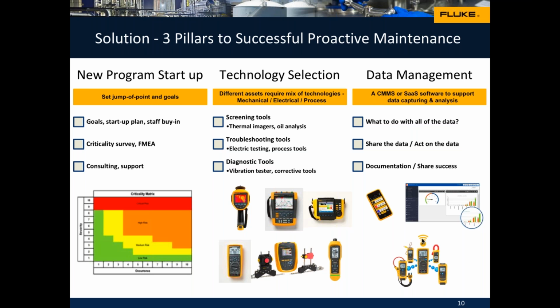There are multiple tools for preventive maintenance, with different levels of difficulty. I think the easier, the better. It doesn't have to be a complicated tool that an expert needs to run. It could be as simple as a basic screening tool. Even a good digital multimeter is a good start, as long as it's done regularly at a good interval, and then you start capturing data.